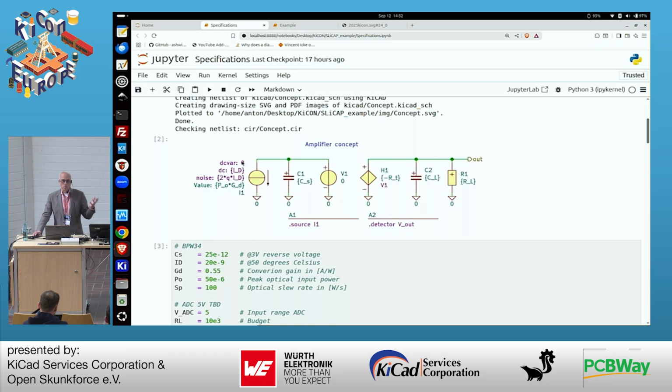But I told you there's a simulation mode in which we can find expressions for the variance of voltage sources, resistors, etc. So in order to get budgets for offsets and tolerances of resistors, for example. So here this current is sensed in a voltage source. The positive current direction in a voltage source is from plus to minus through the source. So it means if I want to have a positive voltage out here, that the current is flowing in this direction, I need to have an inversion.